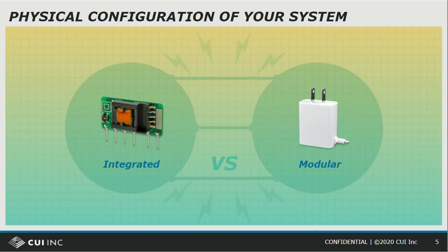Perhaps it may be viewed as more versatile if you do what would be called a modular design, and that is having the power supply outside of the product using an external power supply. In this case, the product can be smaller and lighter without containing the power supply. A great example is your cell phone or your laptop computer. No dangerous voltages need to be addressed by the customer.